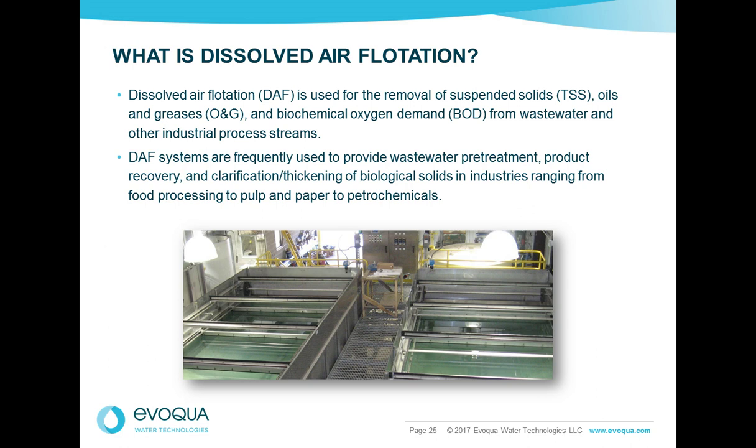Alex is focused primarily on the gravity clarification, which is getting contaminants to settle. Dissolved air flotation, or DAF, is the exact opposite. We're trying to get things to float. As a treatment technology, dissolved air flotation has been around a long time, at least 50 years. It's not as old a technology as gravity clarification, but it is fairly mature.